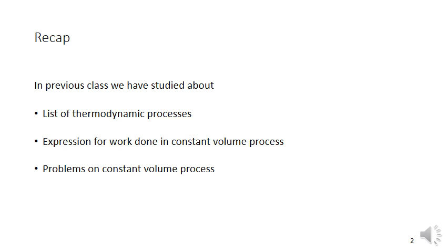Just in 2 minutes I will recap the constant volume process. In the constant volume process we are considering a closed system. A closed system means only heat transfer takes place, there is no mass transfer. The volume remains constant, so the work done by the system is equal to 0.